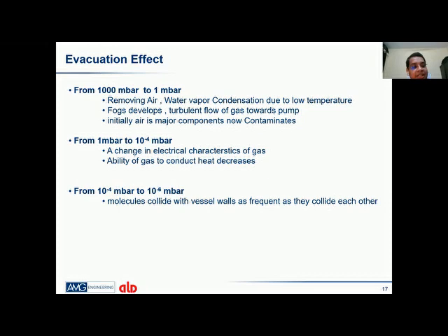It will not only increase the time, it will also hamper the vacuum pumps. So sometimes the oils also have to be changed very frequently. So just to give that picture, at the lower vacuum level, more cleanness of the part is required, and not only the part, the surrounding atmosphere is also equally important.